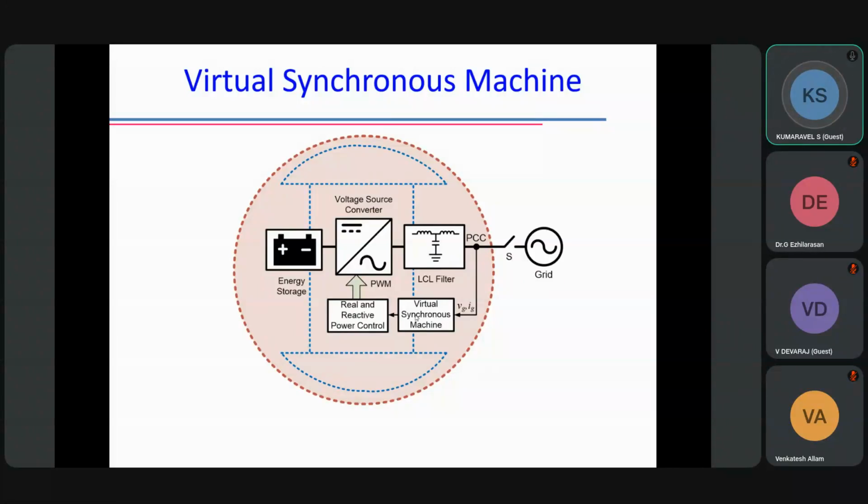Okay. Assume that all of a sudden I'm increasing by 20 megawatt. Okay, it was 50 megawatt. Now I'm increasing it to a total of 70 megawatt. Now what will happen? It will maintain stability. How does it maintain stability? Frequency will drop down, but it will never drop down quickly.